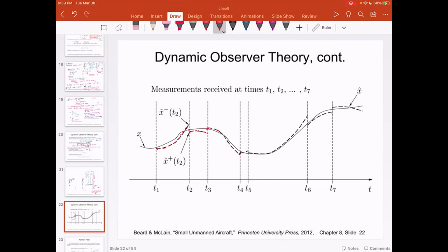With this scheme, you are periodically correcting your measurement. It is exactly similar to what we talked about in GPS. As you know, the IMU is drifting. Every time you get a GPS update, you correct it. But the problem here is the GPS update is not super duper accurate. So somehow you need to combine these two inaccurate measurements and come up with a good estimate.